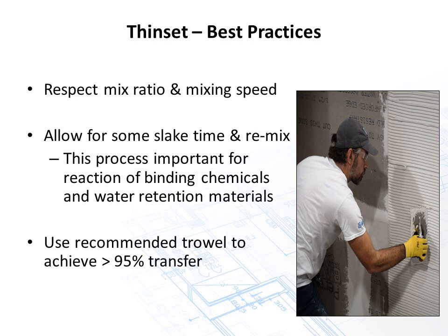Have respect for the water ratio to mixing. Follow the directions. Can't stress it enough. Allow for slake time and remix. That's important if you want to have water retention within the mortar, or I should say good open time. Exterior, ANSI recommends coverage of no less than 95% between the substrate and the tile. That means if we were to pick up a tile, we would see no more than 5% voids.